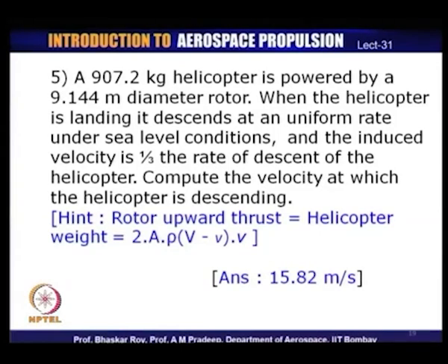A hint is given here for your solution, that the rotor upward thrust is equal to the helicopter weight, and the helicopter weight is given here. So, you should be able to use the momentum theory now to compute the solution of this problem. The answer is given here.